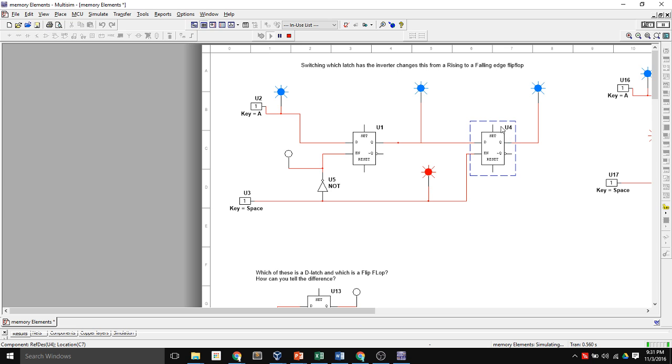And so now, with this latch on and this one off, it doesn't matter what my input to the flip-flop is, because it's not going to go past this disabled D-latch. This is just storing the 1 from earlier, so it's actually not going to change. But the output changes on the rising edge. So notice I just made my clock a 0.